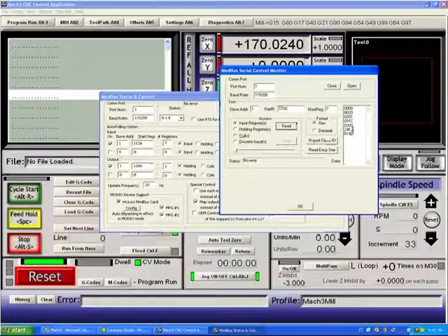This number here, you see the 24E2, which is in the 6th register. That's actually the count of MPG number 2. And if you'll watch, as I press it, it stays at 24E2 until I rotate the MPG, and now the number starts to increment in one direction, and if I turn it backwards, it starts to decrement. So that's just to show you that the ModBus is working.